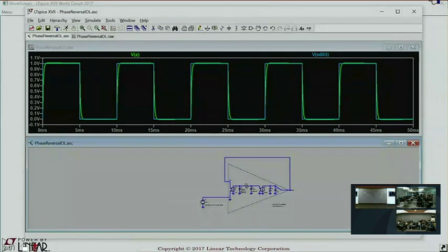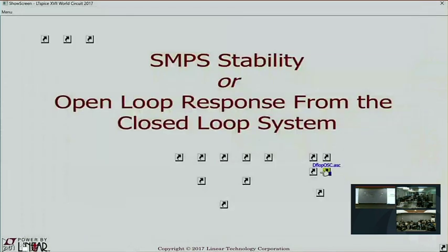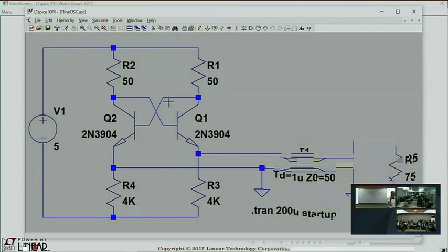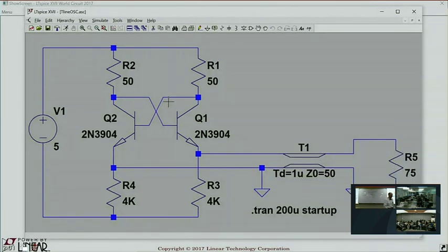Oh, but there's more. I mean, look at this circuit. Okay, here we have a feedback loop. See, here's the feedback loop. The signal goes in here, here's an output, goes in here. This is a feedback loop here. Now, if you analyze that feedback loop, the circuit is stable. It meets the Bode condition. You can prove this circuit is stable if you analyze that feedback loop.